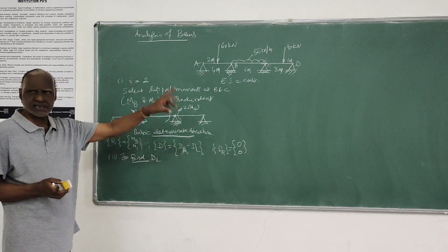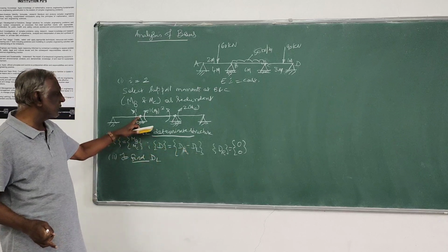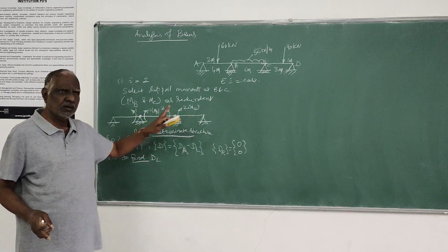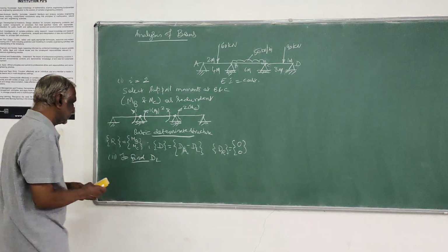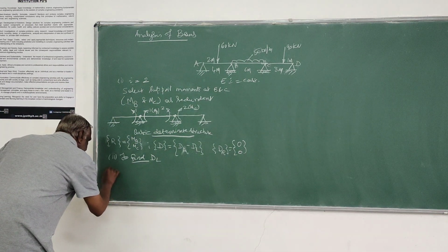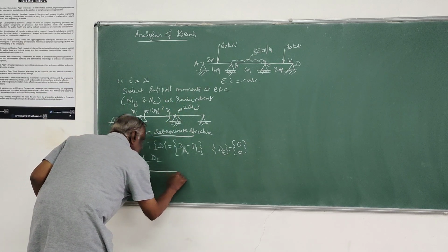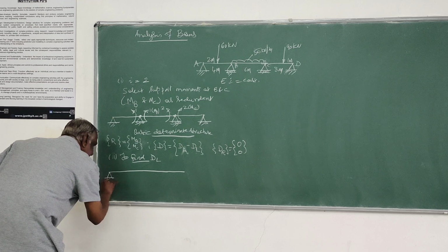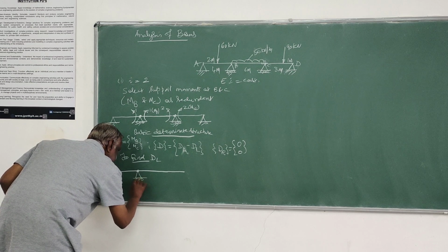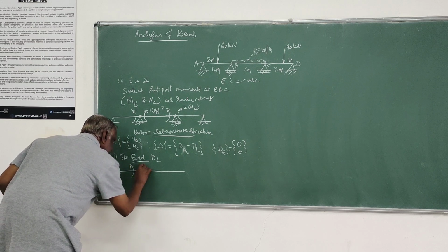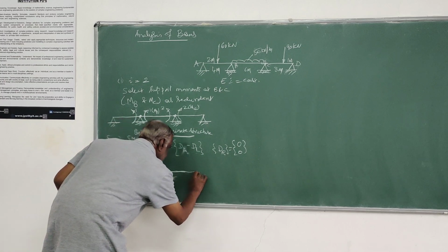That is your basic first step. Second step, this DS, that is the displacements, the rotations along coordinates 1 and 2 on account of the loading given. You have to work that out. So first, we will take up the loading given. That is the basic determinate structure. Like this, we have selected the basic equilibrium structure in this fashion.